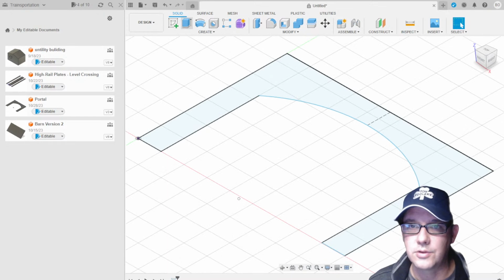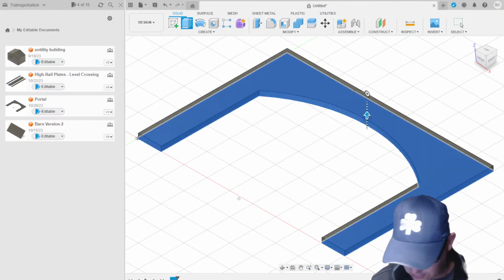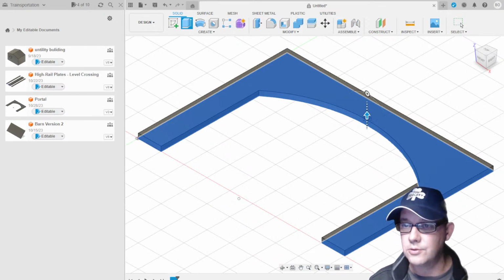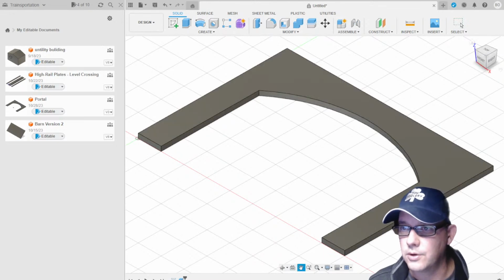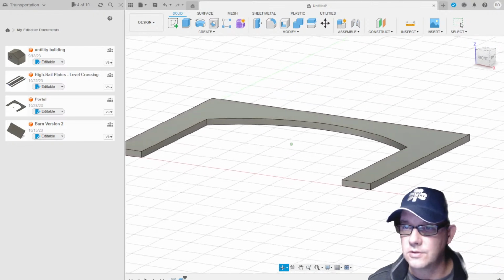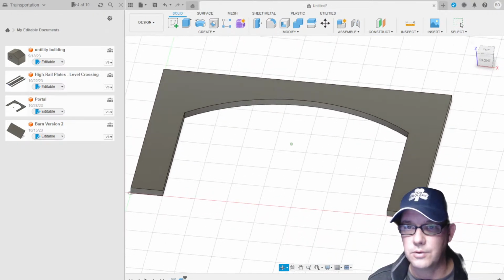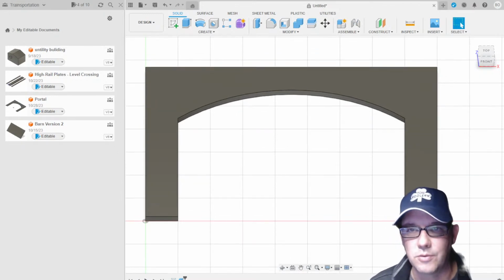And right here, now in 3D mode, I'm actually going to extrude this. So I'm going to use the extrude tool here under the solids menu. I'm going to pick the surface and go up 2 millimeters. Again, I just like to type it in. And now we've got a 3D surface, right? You can see this is kind of a 3D model of a tunnel portal.